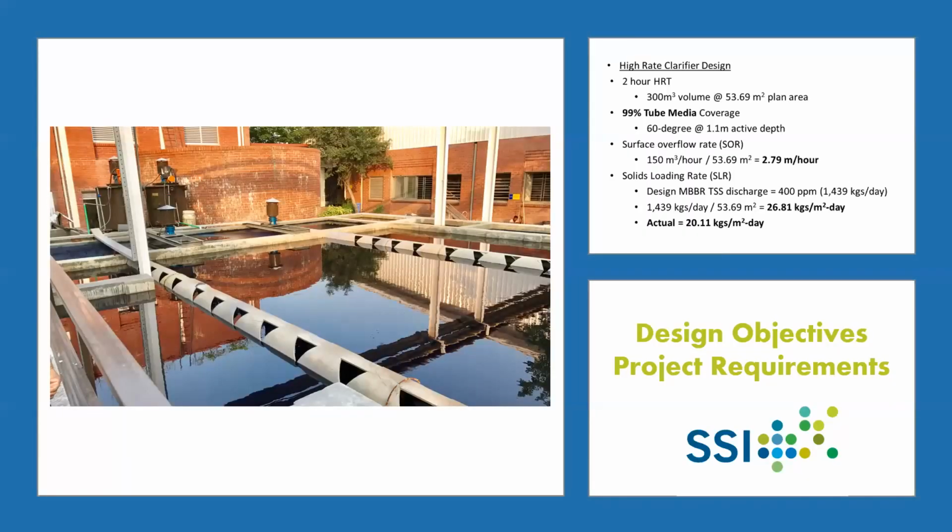The site had an existing clarifier, and we were trying to get more flow rate and better effluent solids, better effluent BOD readings. In a lot of MBBR applications, what we see directly from the MBBR discharge is that the TSS to total BOD ratio is about 1-to-1 in most cases.